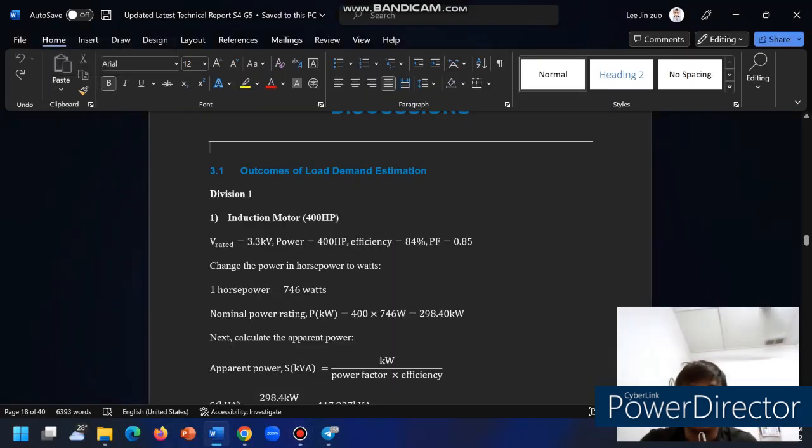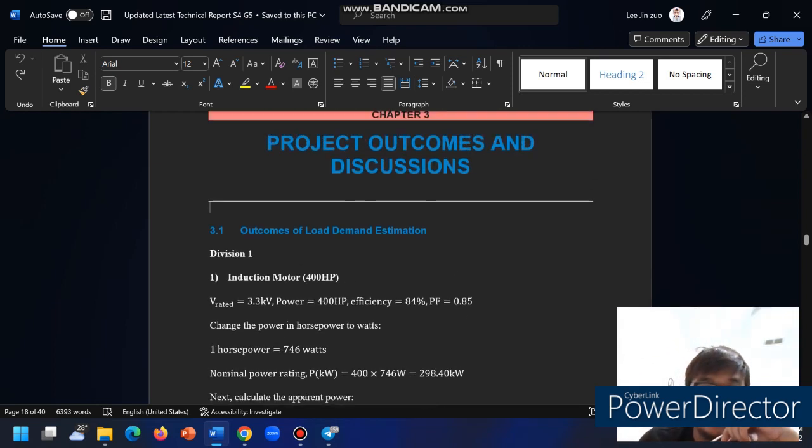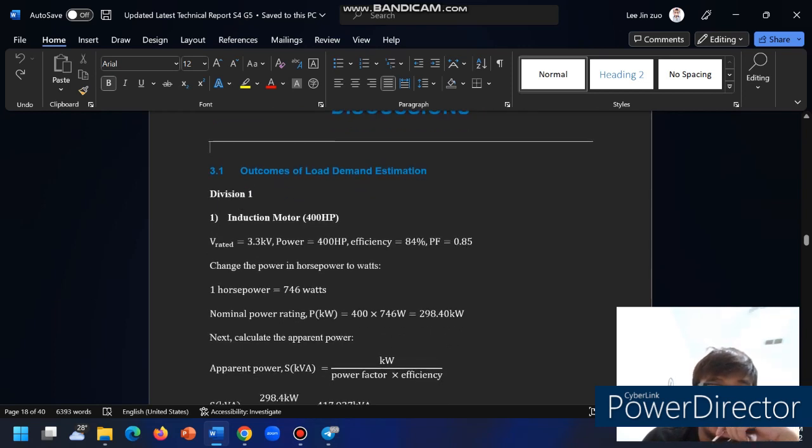A very good morning to all the lecturers who are watching this video presentation today. Now I'm going to present the parts of the outcome for the load demand estimation. For division 1, I have first a 400 horsepower induction motor. The rated voltage is 3.3 kV, the power is 400 horsepower, the efficiency is 84%, and the power factor is 0.85.